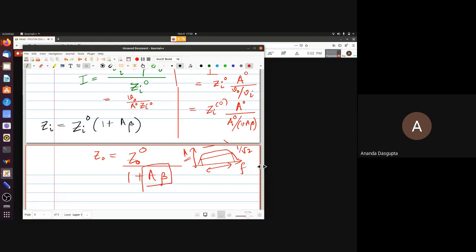It will be Saturday. And there was a question about the beta value to be used for the transistor. For the second question, just take whatever HFE is given for the other part of the question and use that as the beta. And for cut-in voltage, unless otherwise stated, use 0.7 volts. You needed to calculate the bias for one part of the question, and for that you need beta and V gamma. By the way, you will find that the circuit does not depend very strongly on beta. So if instead of 200, which is the given HFE, you use some other value, say 100, you would still end up roughly in the same neighborhood.